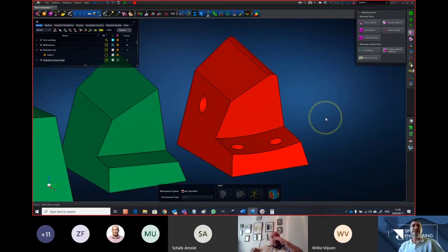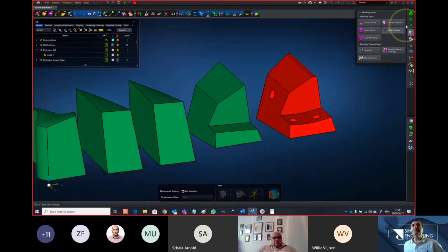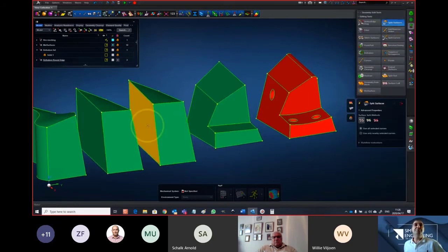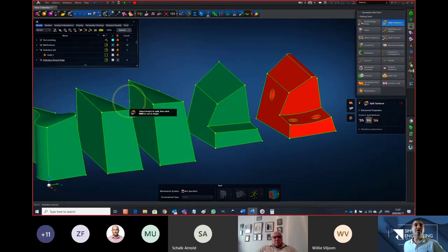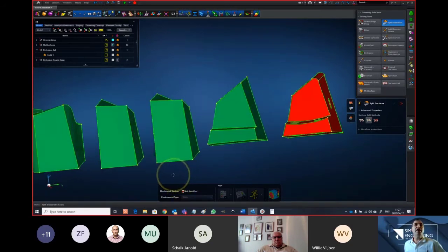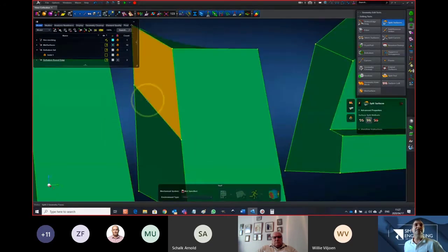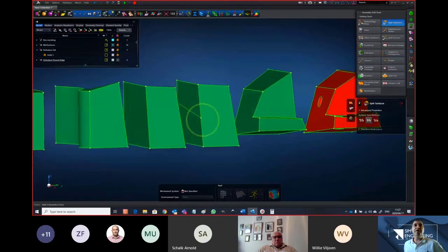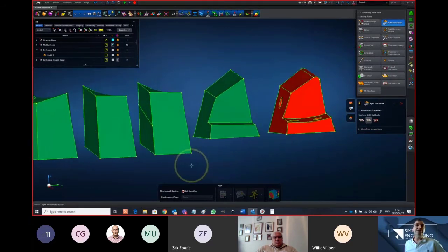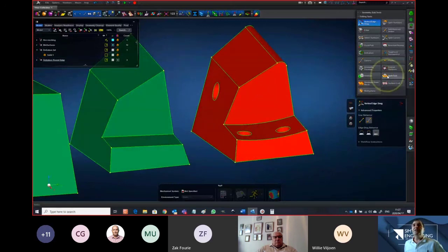So with every release you'll see it has the ability to hex mesh more and more features. Like for instance, there was a stage when it was not possible to have split faces on one side of the extrusion and hex mesh it. So if you had a feature like this on the one face, initially it wasn't able to take that into account, and this body would have been green. As new releases are added, they eliminate a lot of these limitations for us. But this one is still the exception.